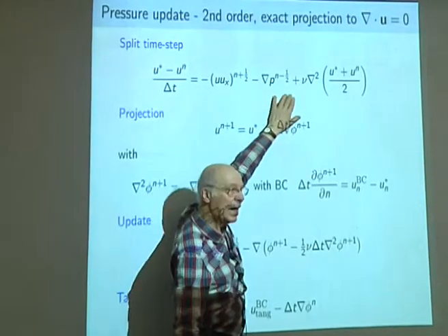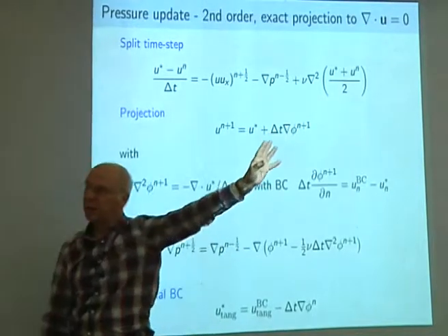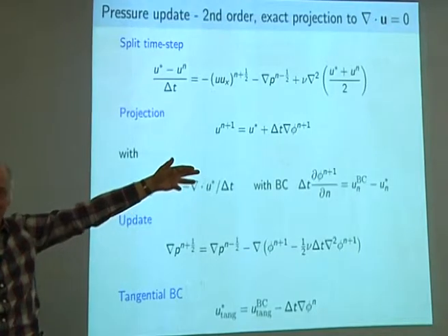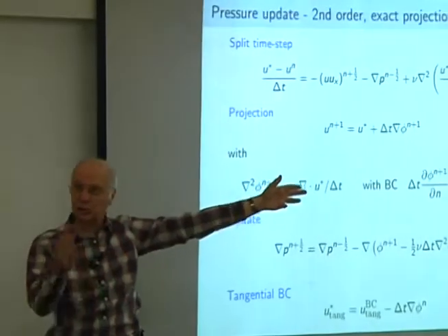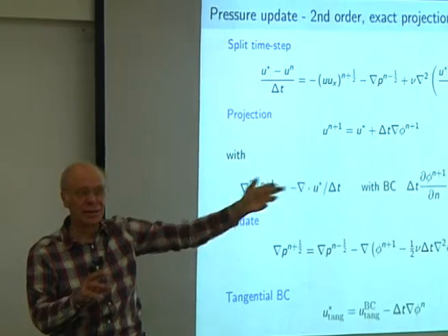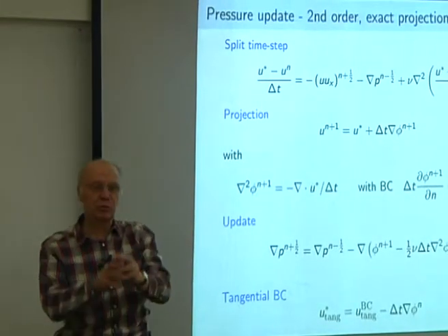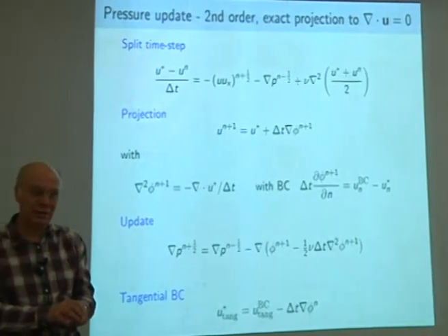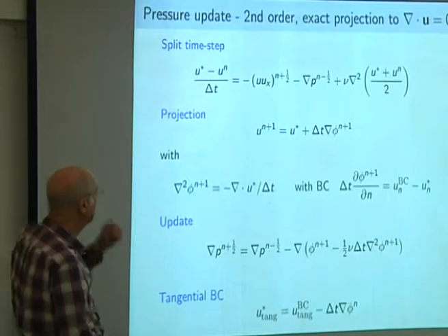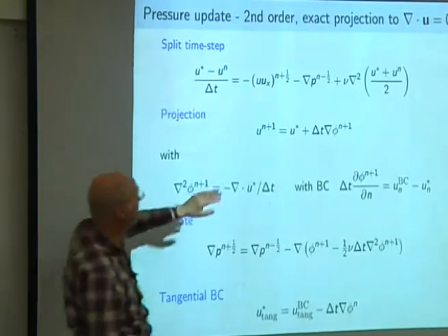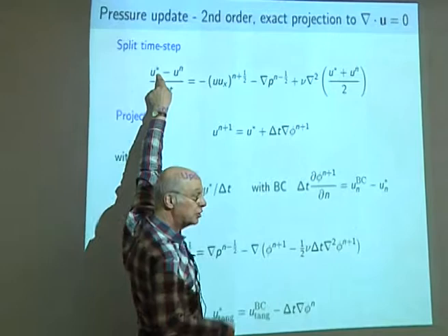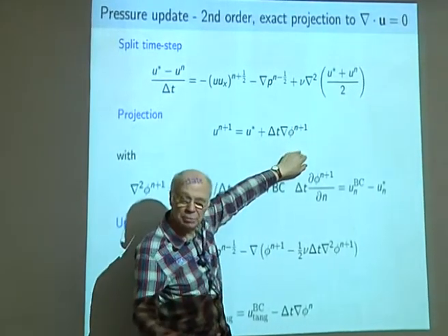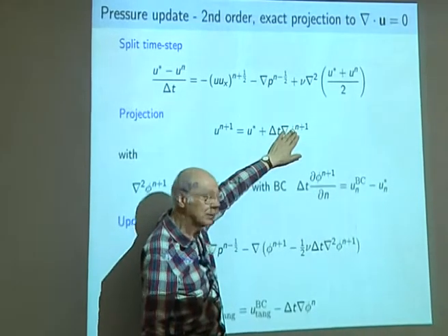So this is an estimate of the pressure from before, and it's only delta T wrong. So we're then going to calculate the extra new bit of pressure, and it's only a little bit. If we do a first order accurate estimate of the little bit, we actually end up with second order accuracy. Right, it is not simple. So the idea is we go from this split time halfway there and add on something that looks like pressure. It is not pressure, and it's only going to be a little thing.